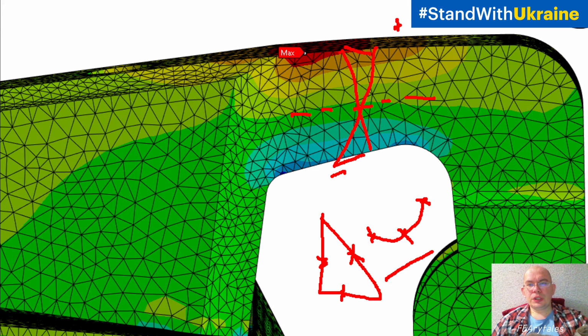So even with one element we can obtain a very physical stress distribution, but in most cases for this type of bending, more accurate result you will have if you will have two elements due to the thickness.